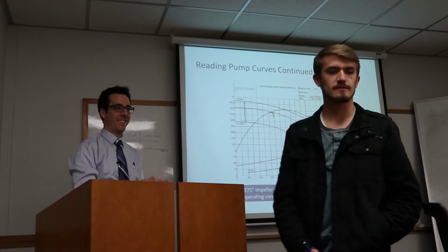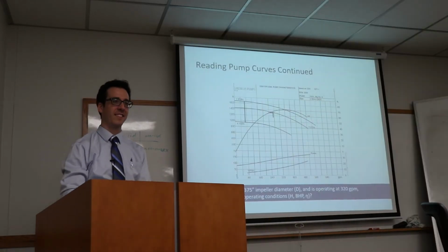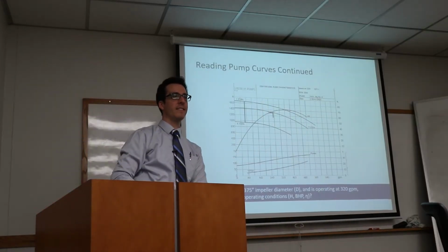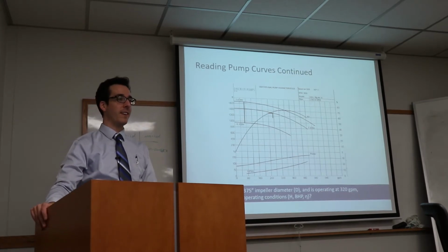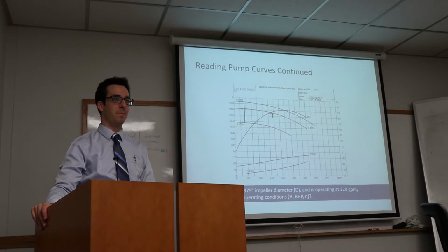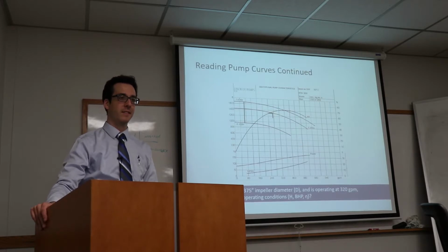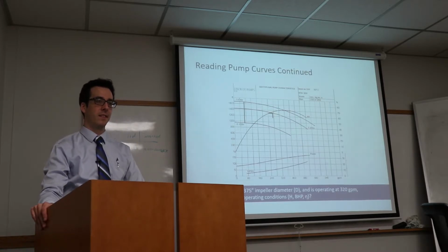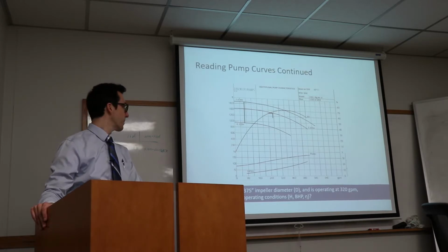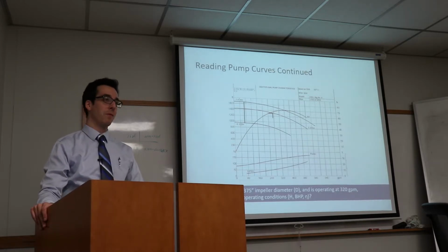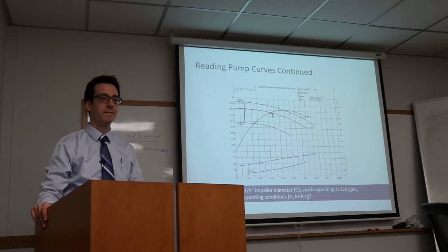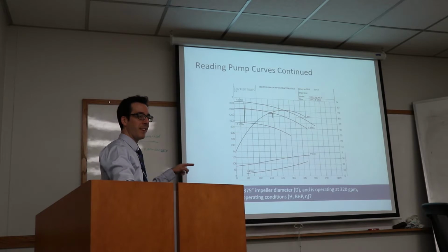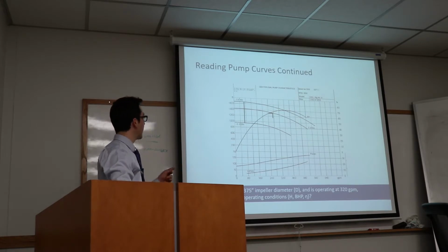Okay, let's give Eric a hand. Okay, yes? So efficiency is only a function of flow rate? No, it's a function of the pump. But right here, the only thing that's changing your efficiency is your flow rate. Yes. If we were to look at a different kind of pump, it would have a different efficiency curve. So on this particular curve, yeah, it's a function of the flow rate, not impeller size.